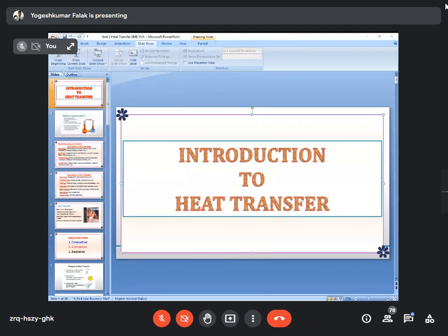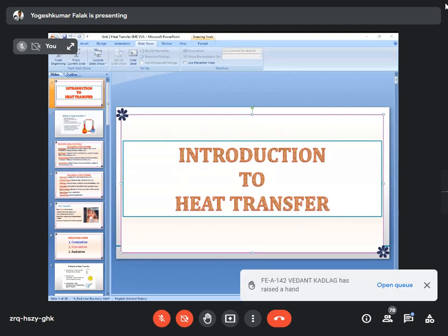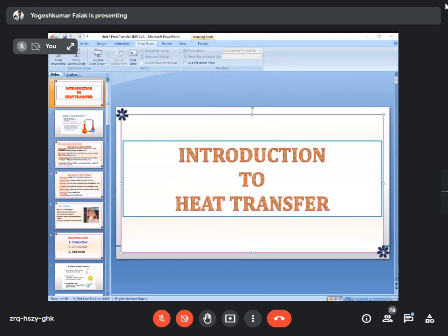So whatever heat there is, it is taken away with that air flowing between those two plates, and the engine temperature is maintained not at room temperature but at a minimum level, so that the piston is not welded inside the cylinder of the engine or cylinder block.